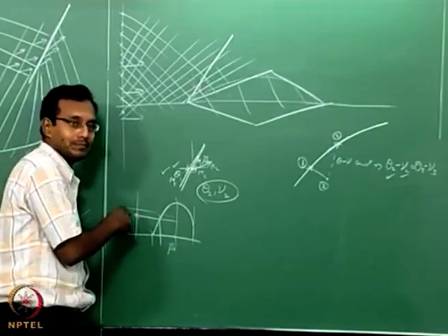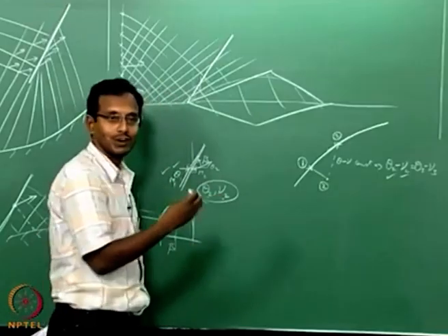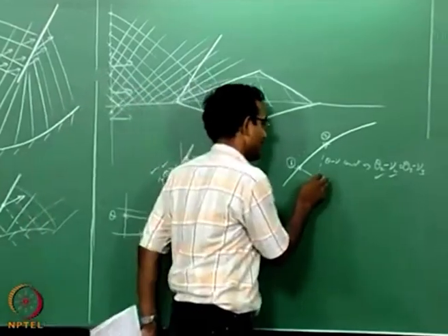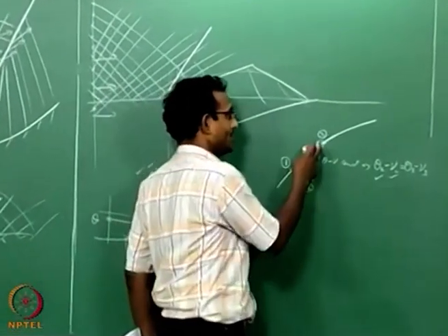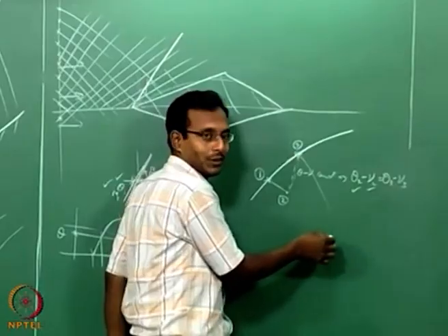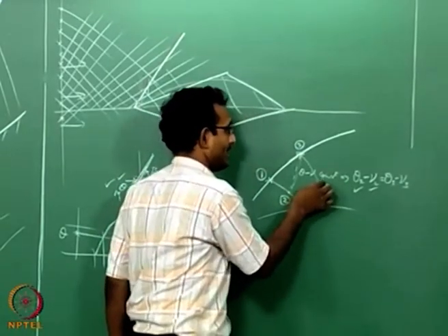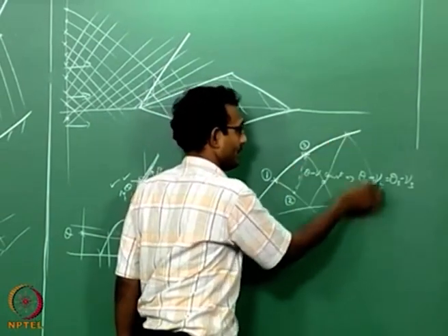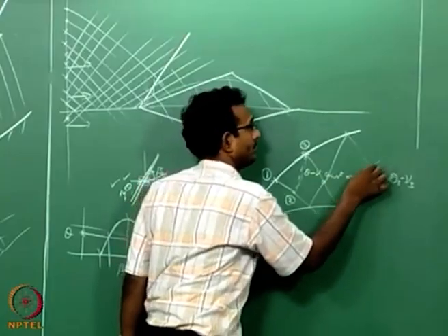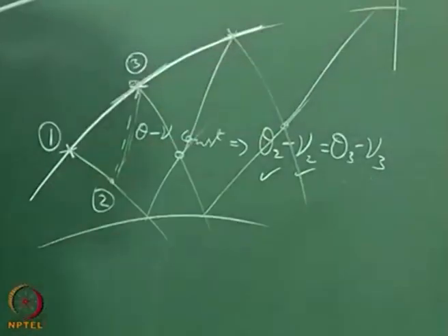and a particular M2 such that I will solve that theta minus nu function to be exactly matching this characteristic line. That is possible to solve. Once I solve, I am sitting here. Now I can send a negative characteristic down here, which will interact with whatever is on the wall here coming back up, and I will get another point which will go up and find the next point. Like that I can keep on solving my oblique shock on some airfoil or something.